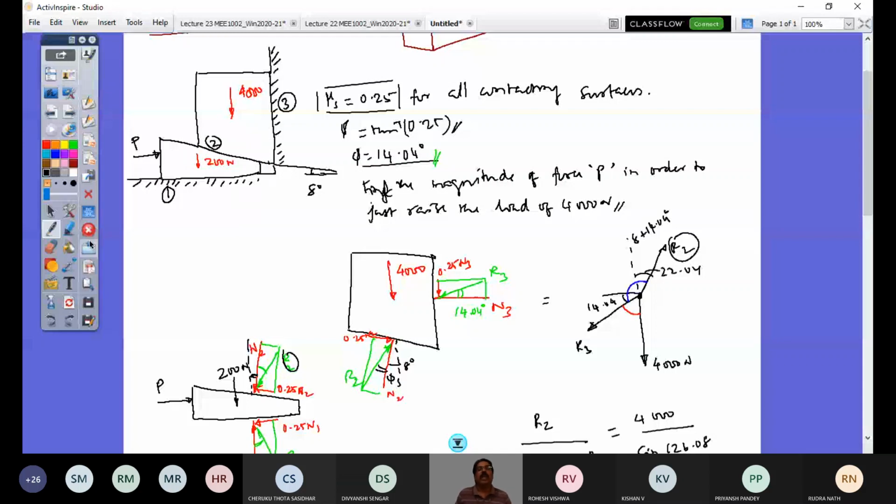Instead of giving this angle 8 degrees, if I give this wedge as 30 degrees, then phi is less and the wedge angle is greater than that. So it has gone beyond the angle of repose. In case I do not have force P, the configuration cannot be possible. So you require force P to prevent the wedge from coming out, and then you have to increase the value of P so that you can raise the load. The problem we have looked at explicitly, block on slope in the last period and in today's first period, you can have a similar problem in the examination.